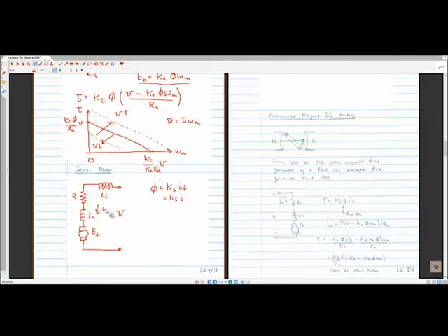So similar statements that we can make here. We have torque, almost exactly as we had before, is k tau phi I, right? But phi is now a function of I as well. So if we now put all these together, we get k tau, ks, I squared.